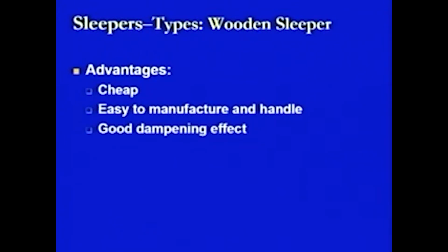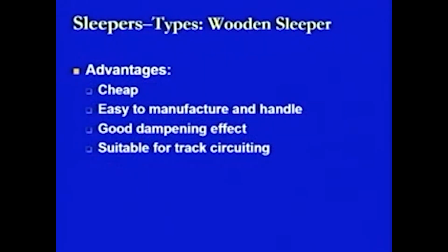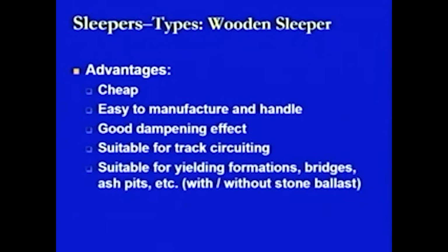This is one of the biggest advantages of using the wooden sleepers. They also have a good dampening effect because of the properties of the wood. Whatever shocks or vibrations are coming, there is a possibility that all these shocks will get dampened out because of the property of wood. Then they are also suitable for track circuiting because of the characteristics of the wood. They are suitable for yielding formations, bridges, ash pits, etc., which are provided with or without stone ballast.